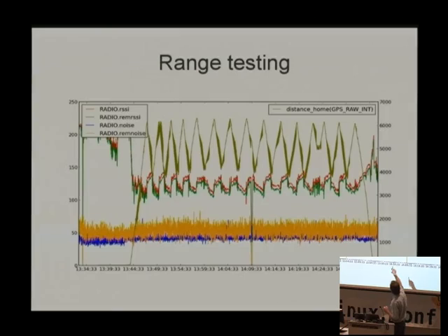You can see there that the link margin we have is of the order of 50 RSSI, 25 dB type link margin. So if you take 25 dB and divide it by 6, that's 4, so 2 to the 4 is 16, 16 times 6 kilometres, so you're talking about 96 kilometres, so 100 kilometre range we could have got, if we'd pushed it right to the edge.